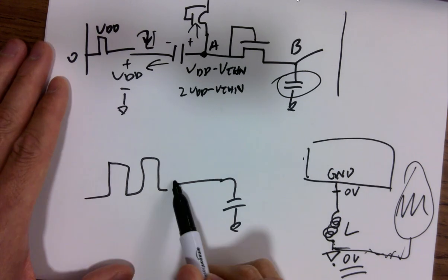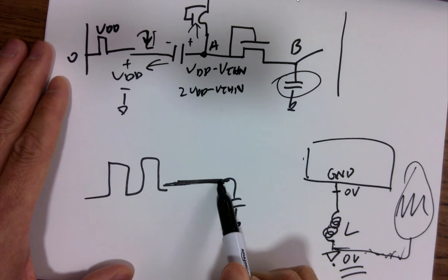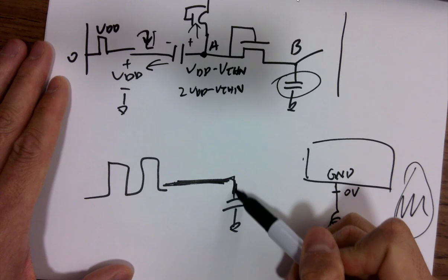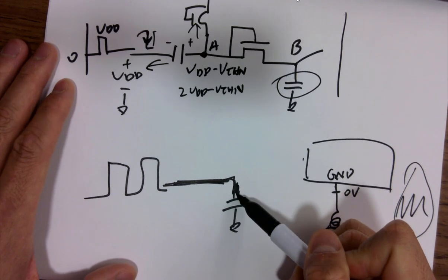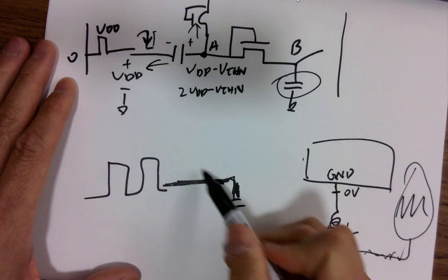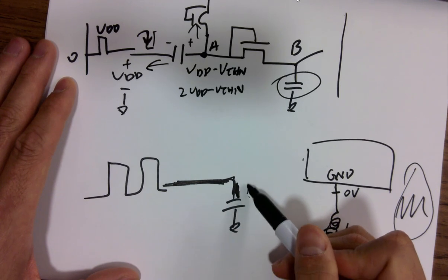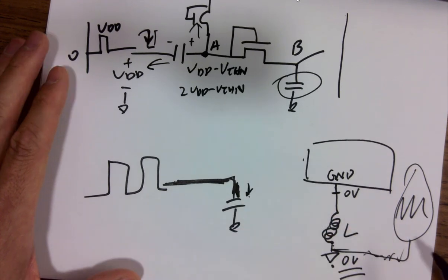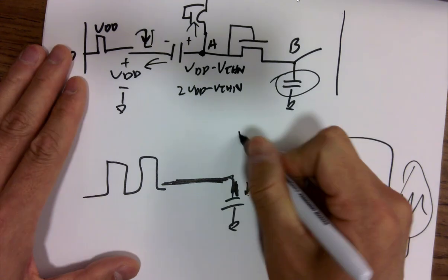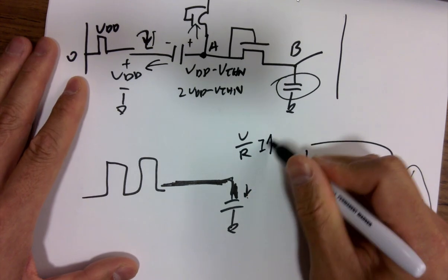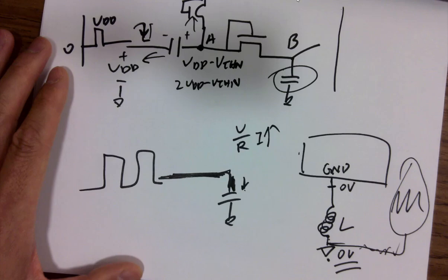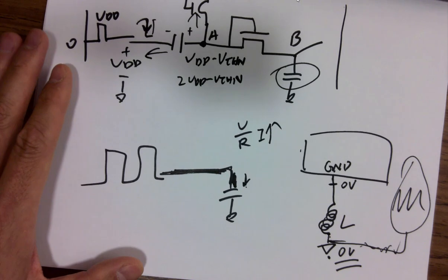But what about this guy? If it's just a wire, we consider this as an ideal metal, right? There's no power and there's no resistor to resist it. It's actually an infinite amount of current being dumped into that. If the resistor is 0, if you do V over R, the current is infinite. So there's no time delay.